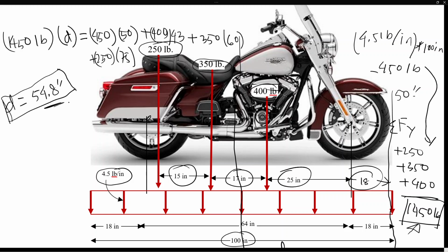However, the goal of this video is to find out the location of this resultant force, which you apply the Varignon principle. The moment produced by the resultant force will be the exact same as the moment produced by the individual components. If you sum all of these moments, it will produce the exact same as the resultant.